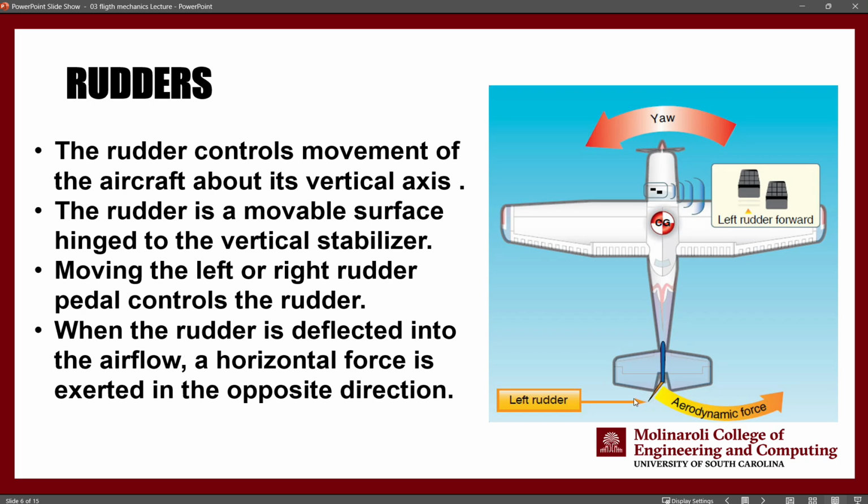And this movement, this rotation, is going to essentially create a higher curvature in one direction or in the other direction, which in turn is going to create a higher aerodynamic force in one direction, which in turn is going to cause a movement of the nose in the left and right direction. So the benefit of this type of turn is that the wings of the aircraft are not rolling at all. Which makes it easier to turn on the ground without harming the wings of the aircraft.